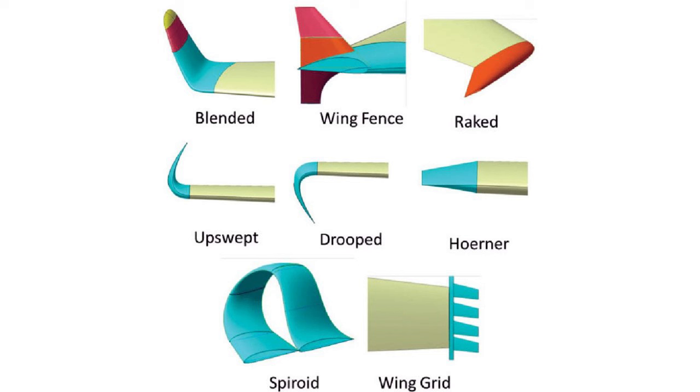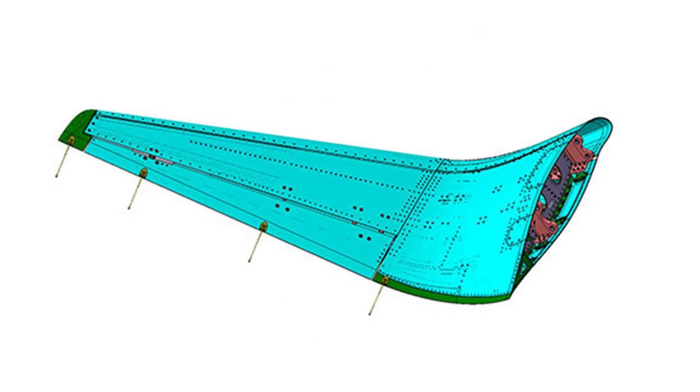Winglets aren't a perfect solution, and they can cause issues if they aren't designed with a lot of care and precision to overcome the adverse effect of the added weight, complexity, part count, and profile drag. You'll hear a lot that because wingtips add weight and generate a maximal bending moment at the root for any given weight, since they're the farthest you can possibly get from the root, that the wing structure has to increase in weight to accommodate for the loading increment due to the addition of a winglet.